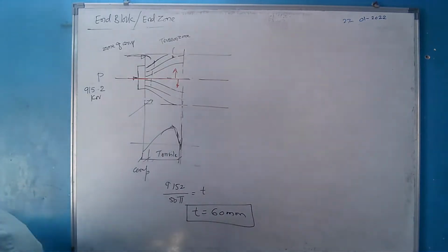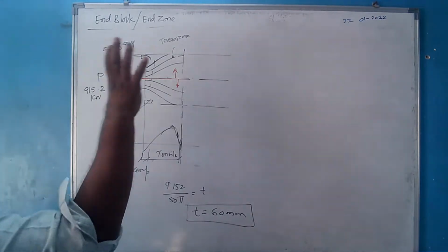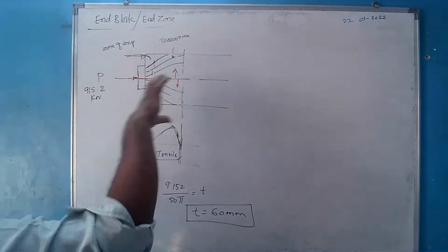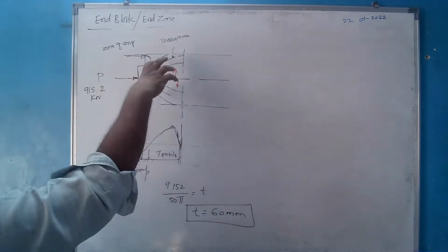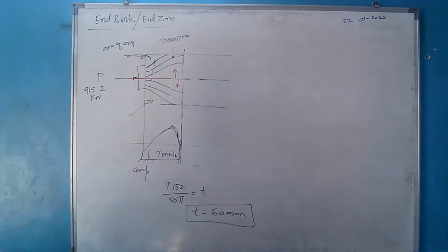एंड ब्लॉक में तीन प्रॉब्लम्स आ सकते हैं. प्लेट पंच हो सकता है, प्लेट में शेयरिंग हो सकता है, या एलिमेंट एंड ब्लॉक में बर्स्ट हो सकता है. हमको तीनों के लिए रेजिस्टेंस देना पड़ेगा.